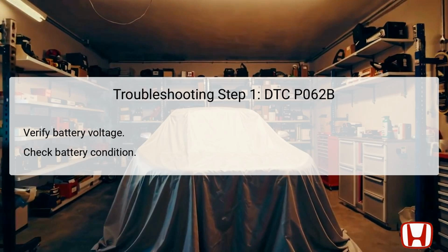If the battery is below this threshold or is in poor condition, it can lead to erroneous fault codes and malfunctions. Conducting a comprehensive battery test can reveal whether the battery's voltage and overall health meet operational standards, providing a clear path for further diagnostics.